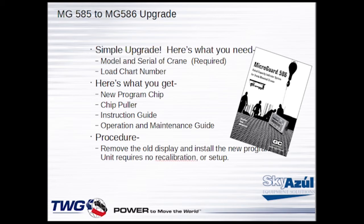Again, it's a simple package. What you need is the model and serial of the crane, the load chart number. You're gonna get a new program chip, chip puller, instruction guide, operation and maintenance guide. And all you have to do is remove the old display, install the new program chip, and the unit requires no calibration or setup. You're off and you're running. So that's a good upgrade.